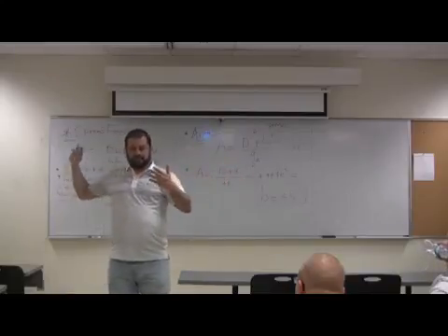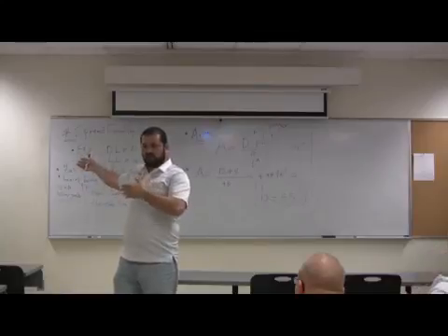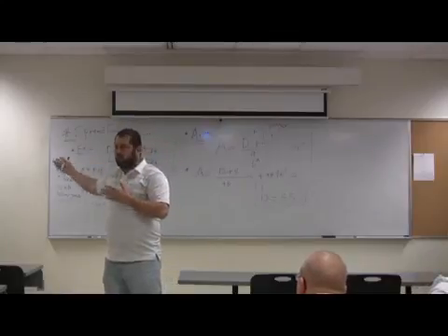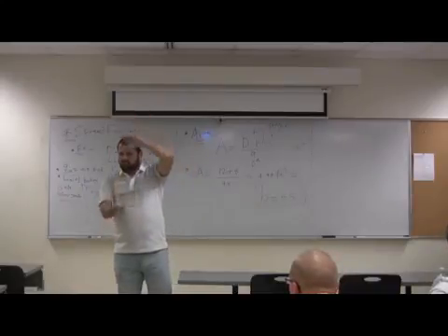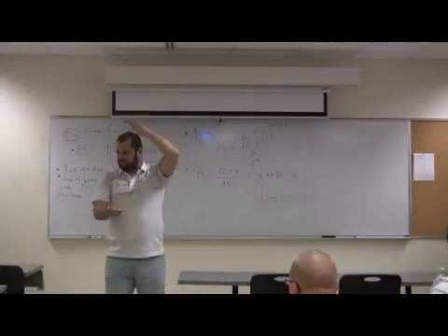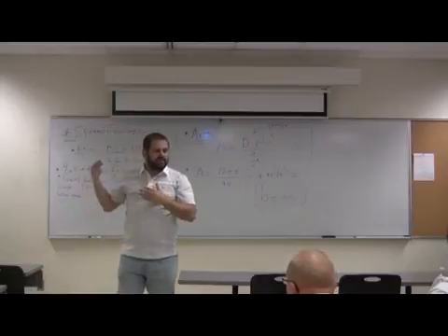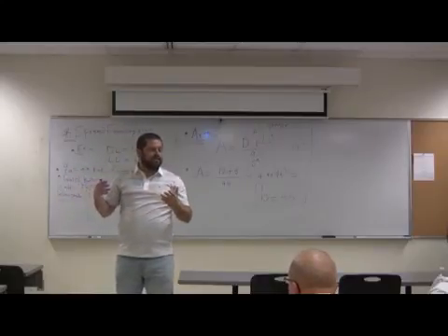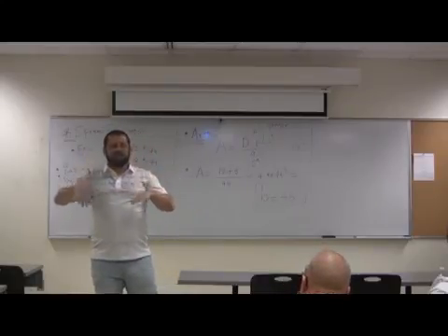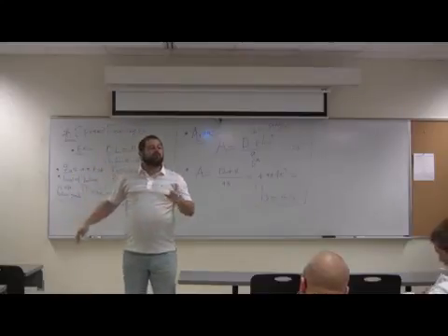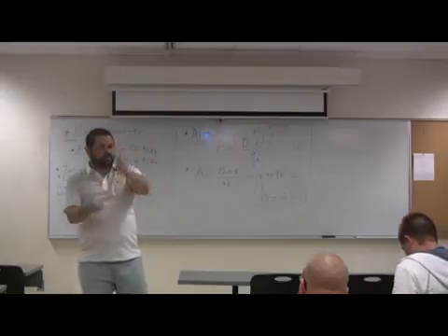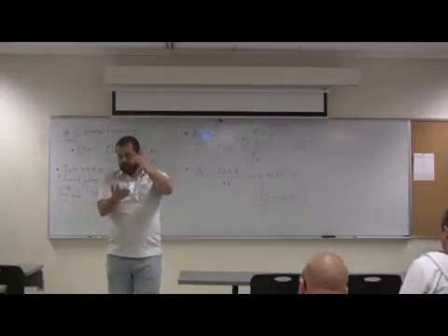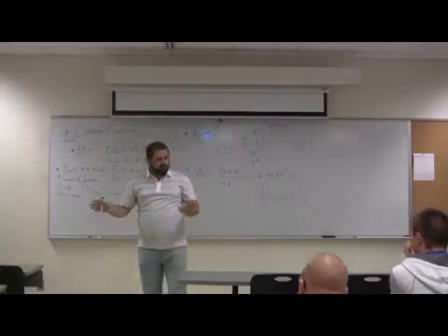So you can add to that 3 times 0.1. Or sometimes you take an average. If you have a foundation depth of 5 or 6 feet and you don't know whether the footing thickness is going to be 2 feet or 1 foot, you say, I'm going to multiply that depth by 0.125, or 125, an average unit weight of concrete and soil. That's a good conservative number, 0.125, if you want.